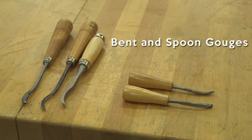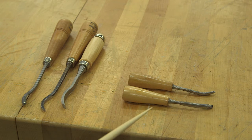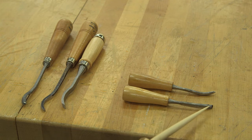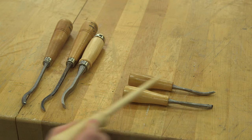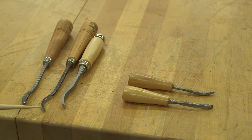Bent and spoon gouges are used to get into inaccessible spots on a carving that a straight gouge cannot reach. A bent gouge has a shaft that is completely curved. A spoon gouge has a shaft where the final 1.5 inches of the shaft is deeply bent in a spoon shape.